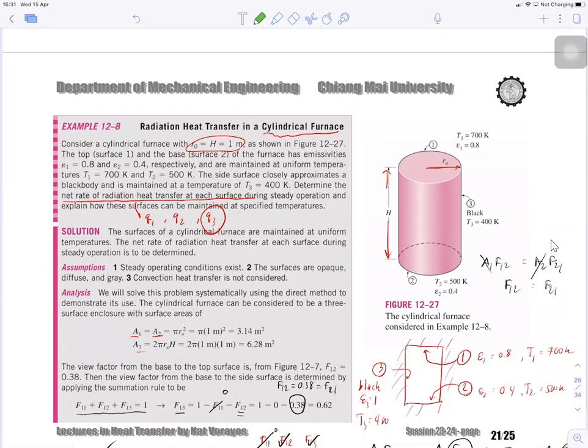Great, superb. If you cannot, you just use the pressure drop. I'm specifying the pressure drop, that's fine too. There's the pressure drop mentioned for the tube bundle. If you choose your heat exchanger as the shell and tube, when flow goes over the shell and tube, it's going to drop some pressure. And there's already an expression for that.